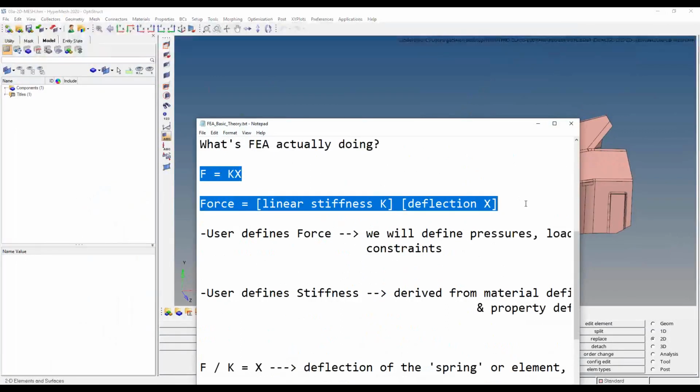That's responsible for making sure we're representing the parts that we want to model correctly and as accurately as possible. And really, though, it's the mesh and the elements that we're creating that are going to have the biggest influence on how that stiffness matrix is being created. As a good rule of thumb we can carry with us from today moving forward, as long as we have a high enough quality mesh and we've set our materials and properties correctly, we should feel pretty confident that we have a digital twin, or virtual twin, of the part that we're trying to represent in our HyperMesh model.